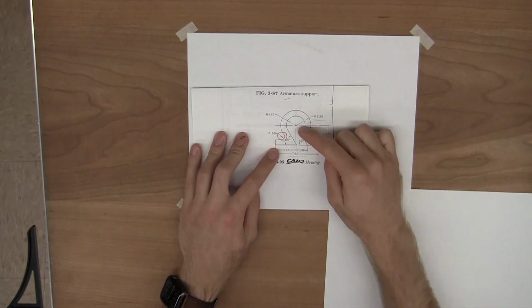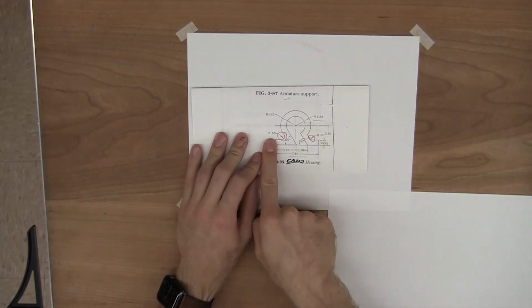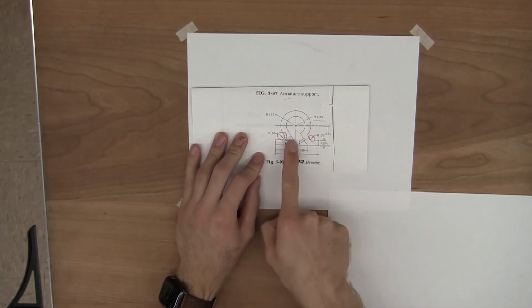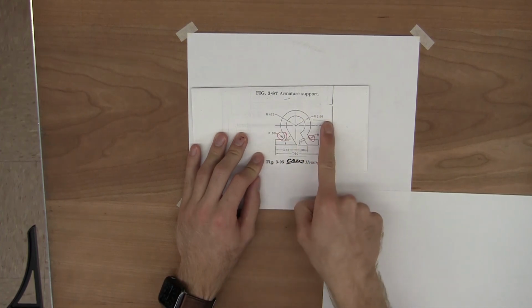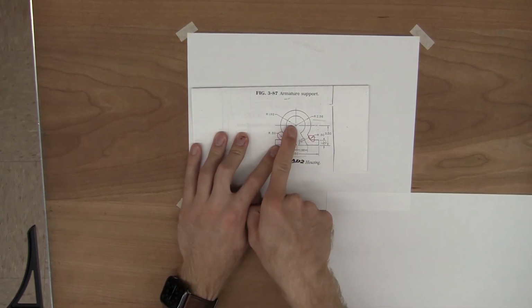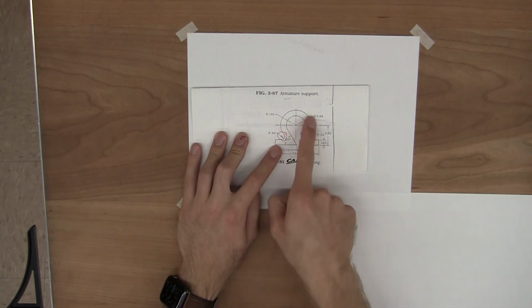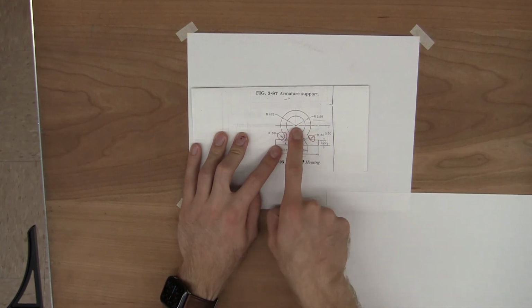A drawing like this is not the same as it is top to bottom or left to right. And also the center of the actual drawing is not the center of that circle. So we're going to start out with drawing these arcs, so we need to find that center point first. The first thing that we have to do is find the total width and the total height of housing.